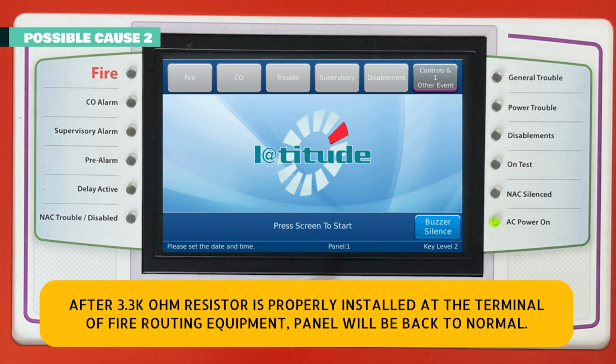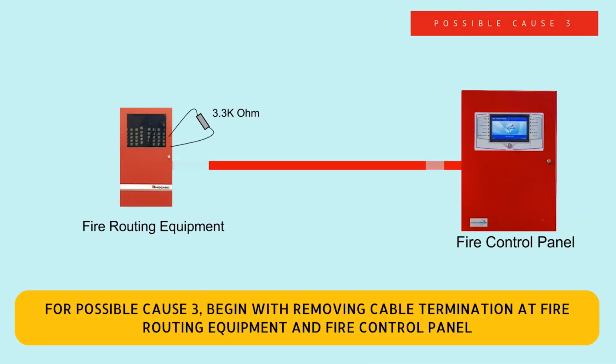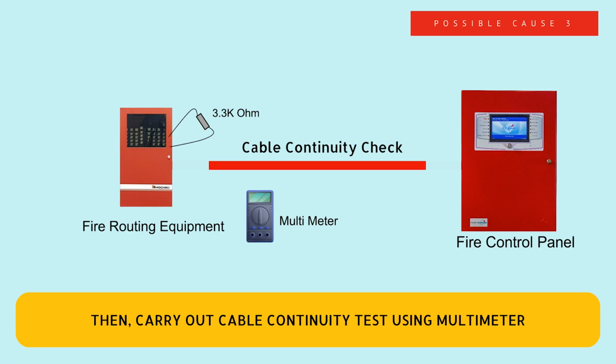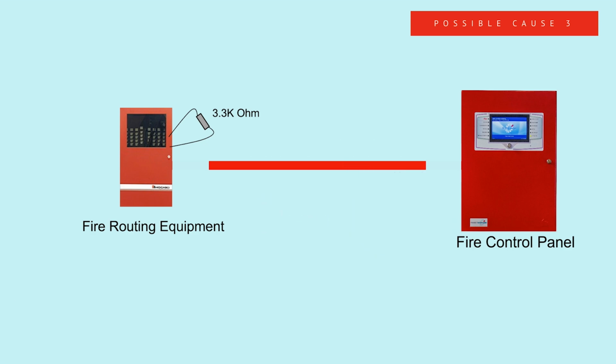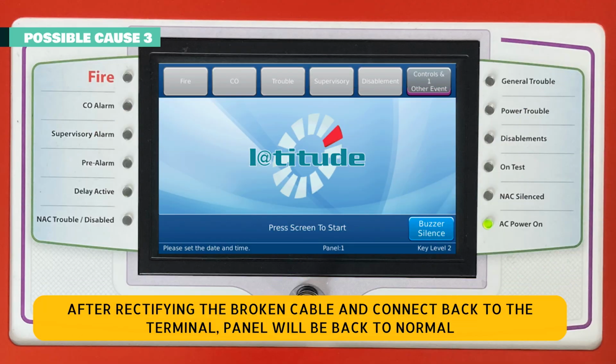For possible cause 3, begin with removing cable termination at Fire routing equipment and Fire control panel. Then, carry out cable continuity test using multimeter. If continuity test found cable open, broken, find out and connect it properly. And then, connect the cable at Fire routing equipment and Fire control panel. After rectifying the broken cable and connect back to the terminal, panel will be back to normal.